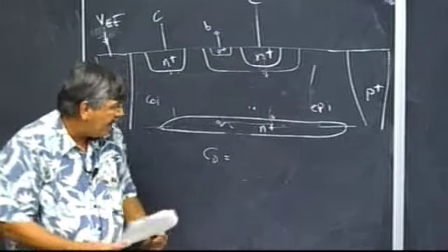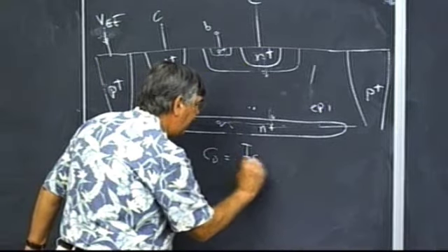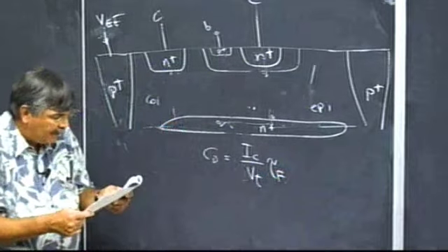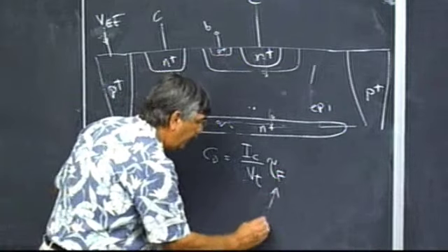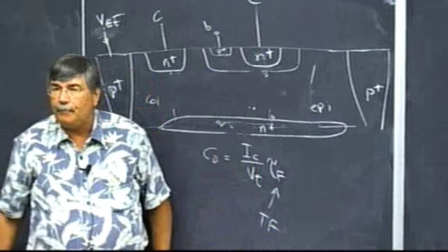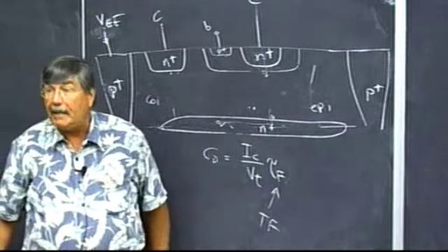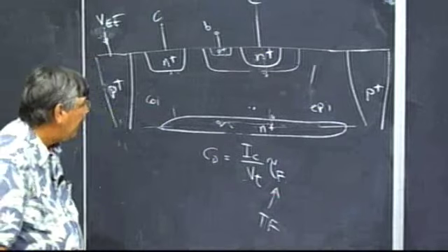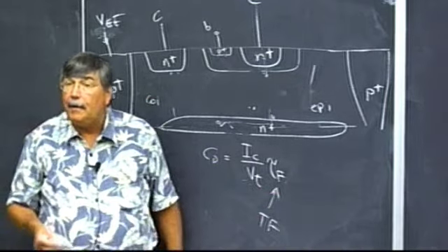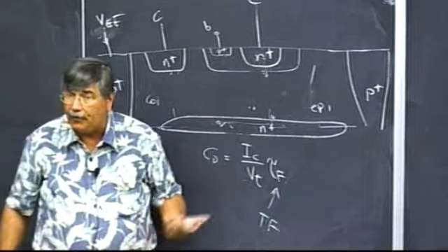For reasonably high currents, we model this as IC over the thermal voltage times the parameter called tau sub f, and the SPICE parameter is TF. All the SPICE parameters have alphanumeric names. And that is, again, something that some grad student or somebody has to go out and measure. It's in seconds, picoseconds probably, for a realistic value. That gives us the main capacitance, which is really the business end of the transistor. If you're going to vary the current that's flowing in the device, you have to vary the charge that's in the base. That's just fundamental.